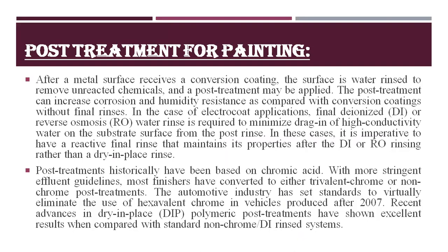After a metal surface receives the conversion coating, the surface is water rinsed to remove unreacted chemicals, and post-treatment may be applied. The post-treatment can increase corrosion and humidity resistance as compared with conversion coatings without final rinses.